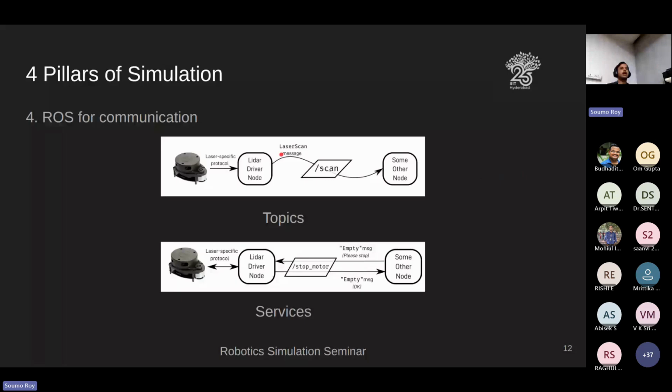And you saw the LiDAR sensor, which shoots a point cloud beam. And this can be a message. This is sent to a node. A node is a small program that can help communicate to and fro with a system. So you would send this message data over a particular topic, which is called a scan topic in the case of the LiDAR sensor.